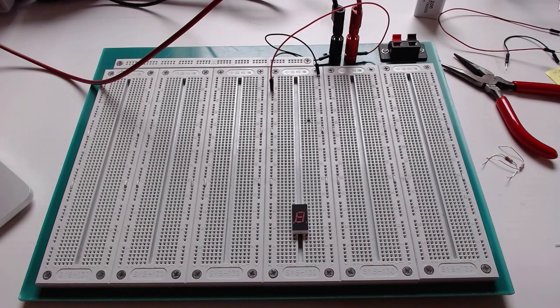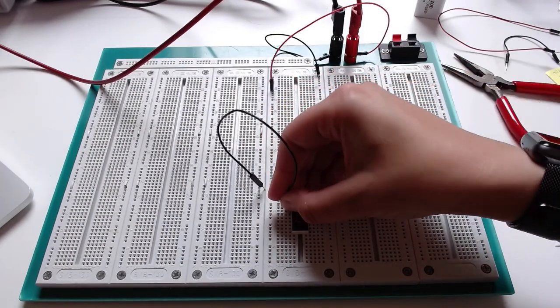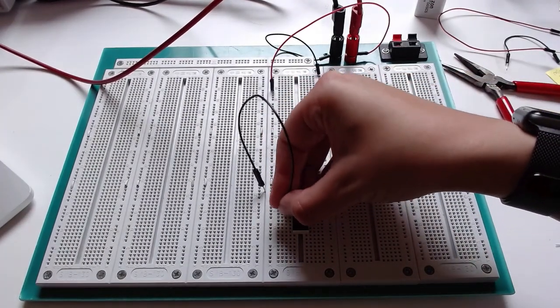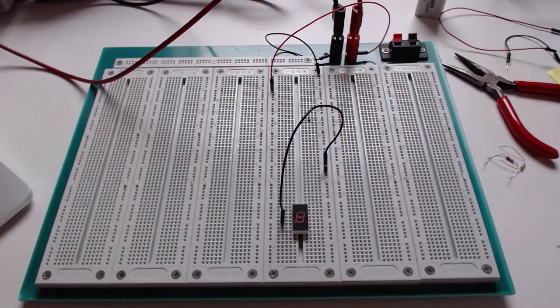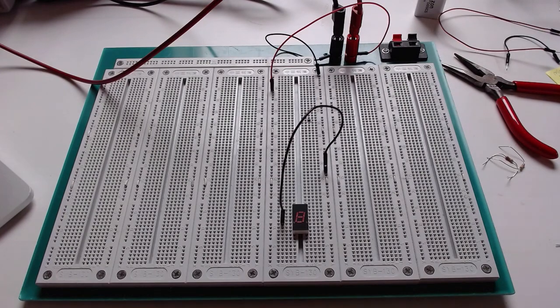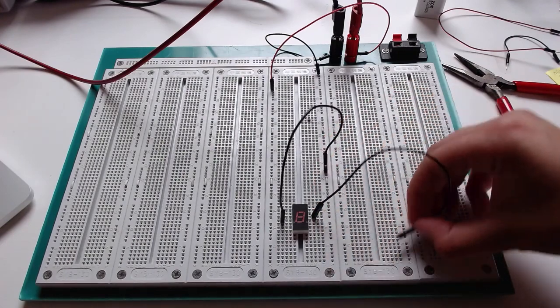So we need to look at the pinout diagram to figure out how to connect this thing. Okay, so pinout diagrams are really important, as we will learn throughout the class. There are 2 common cathodes on this specific chip, so we need to make sure that they're both connected. Pins 4, so this is 1, 2, 3, 4. Pin 4 and pin 12 are the cathode pins. So these need to both be connected. You can't just do one, they both need to go.